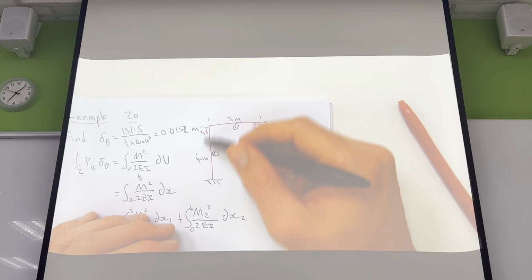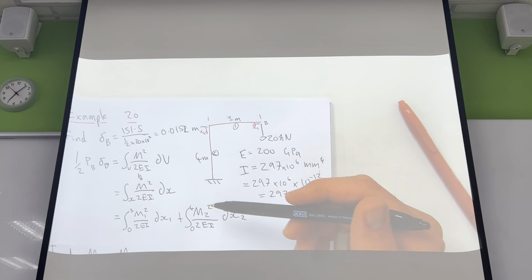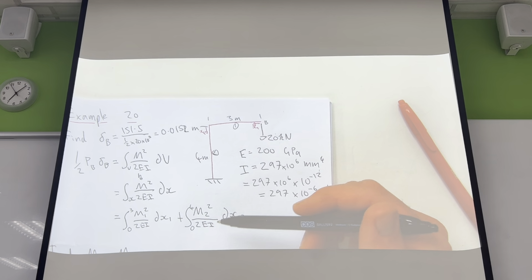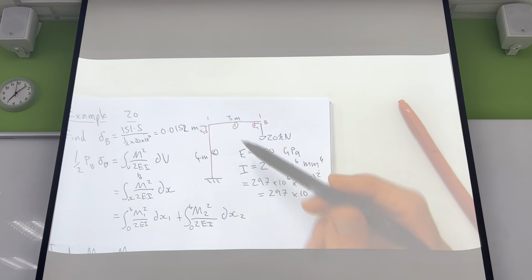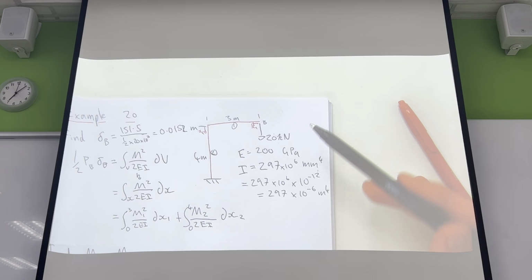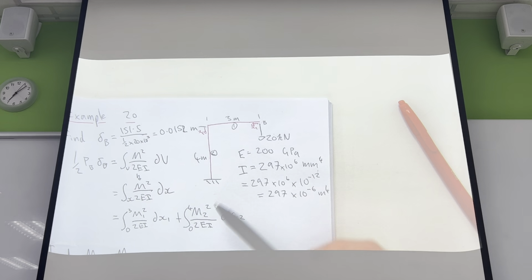But for a system like this, you can't really do this using the previous method that we utilised, where we took the integral of M twice and did it that way. You couldn't do this method, but because we're just doing an energy-based method, we can use it to find the deflection at that location.